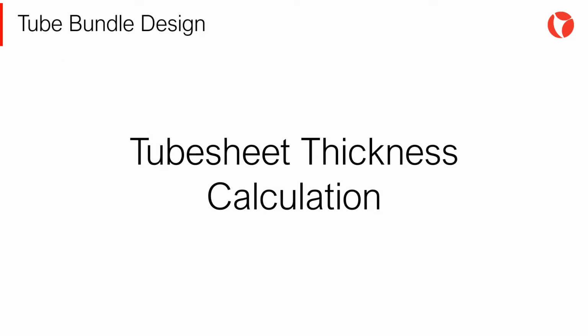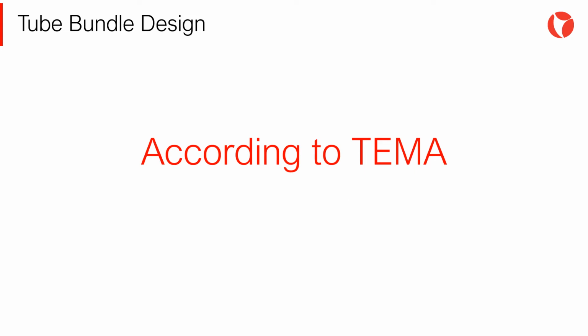Tube sheets are a key element in heat exchangers. For that reason, the design and calculation must be carried out taking into consideration all factors that can increase the thickness, such as slots, corrosion, grooves, coatings, etc. Tube sheets can be designed and calculated according to the TEMA and ASME codes. Depending on the client and project requirements, one of these two design codes is applied. The TEMA code design and calculation procedure will be described.